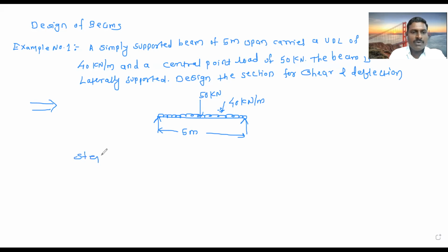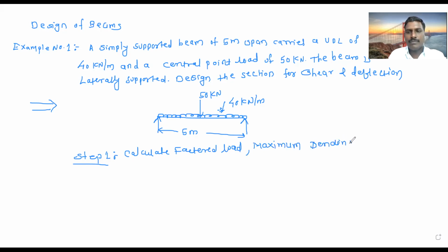So now follow these steps. Step 1, follow the steps for design of beam. What is step 1? Step 1 is calculate factored load, maximum bending moment, and maximum shear force, for whatever loading is given.